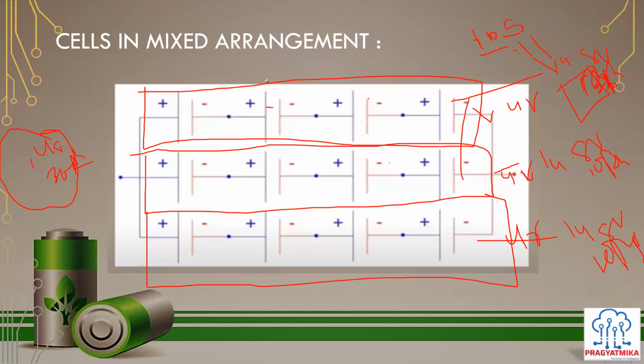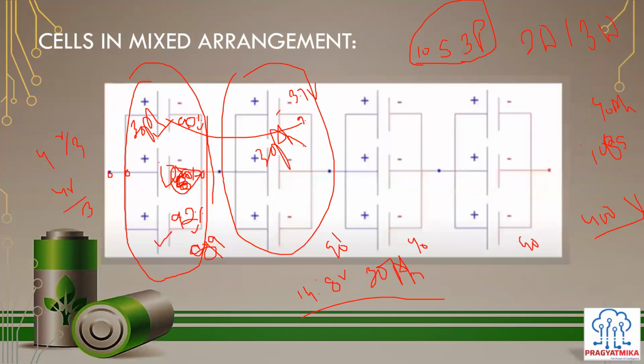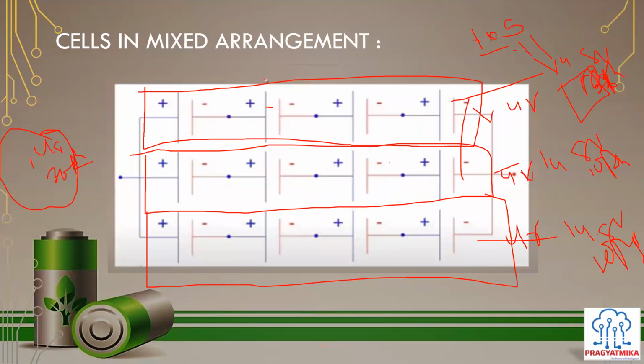So individual cell balancing does not depend on the connections of these cells, right? Exactly. The BMS only has the feasibility of measuring the voltage through the connection. It works on the individual cell, but because you have connected the cells in parallel, this whole module is considered as a single cell. So this is one single cell for the BMS. Whether you have connected it in a parallel or series arrangement, it is irrelevant for the BMS from the connection perspective.